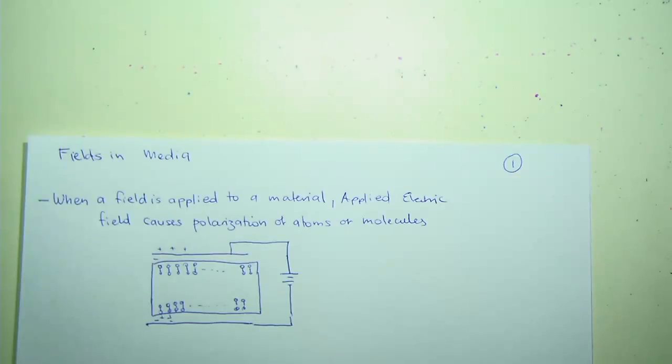Now, in order to increase the dielectric constant of that material, people are beginning to go to hafnium oxide and things like that, which have high dielectric constants but also lower leakage currents. But here, suppose you've got a material, you apply a field across it, you actually get redistribution of charges within that